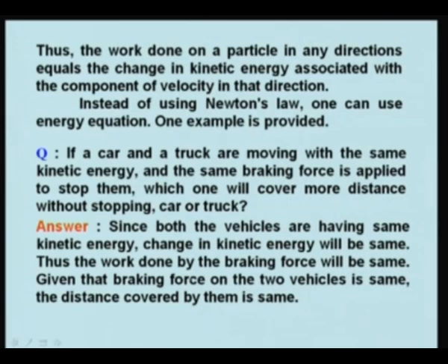Since both vehicles have the same kinetic energy, the change in kinetic energy will be the same. Thus, the work done by the braking force will be the same. Given that the braking force on the two vehicles is the same, the distance covered by them is the same.